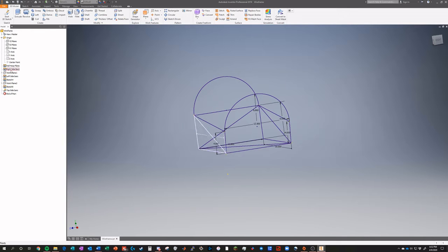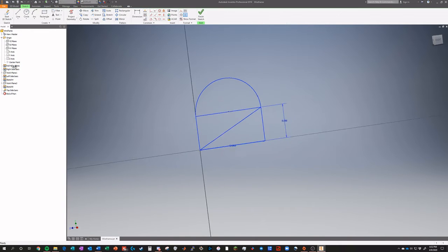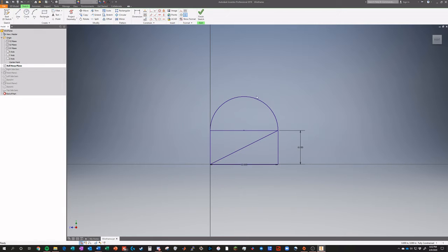So what I'm going to do is I'm actually going to go back into that original sketch, and I'm just going to right-click this, and I'm going to click construction, just so we can still use it, but it doesn't necessarily appear as a piece. So I'm just going to split this into 3 segments, and basically I don't want to split it into 2 segments because that will be a little bit oversimplifying. But if I do too many more than that, it's going to take me a really long time, and you start getting diminishing returns in terms of accuracy. So kind of use your best judgment here. I wouldn't do too much more than this much bend.